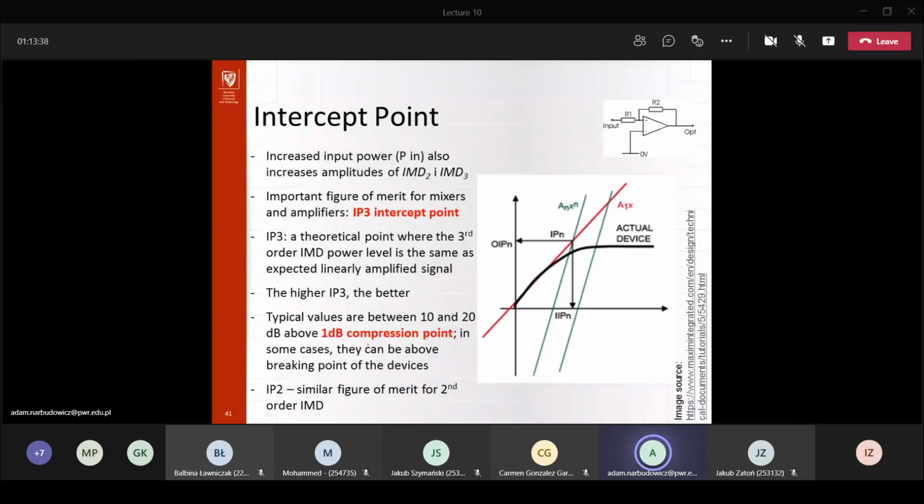So we're talking here both harmonics and intermodulation. Whereas for intercept points, if you reach the intercept point, that actually means you have the same power for intermodulation products as you would have for your amplification. And actually your amplification is compressed, so it will be much lower. So that basically means you're really in huge trouble even before reaching IP3. So IP3 is useful for modeling behavior, but of course, it doesn't mean that you can operate up to the IP3 intercept point. That's not the idea here.